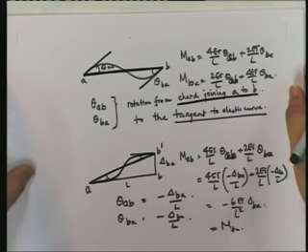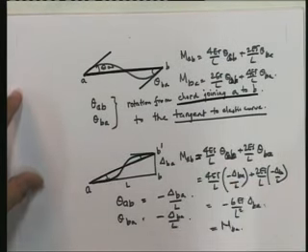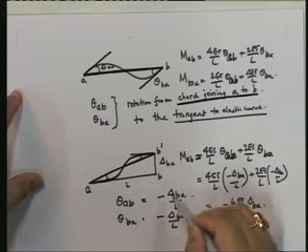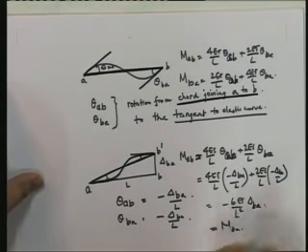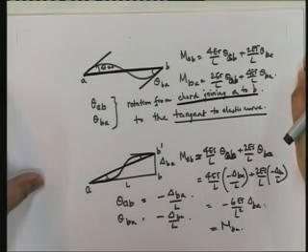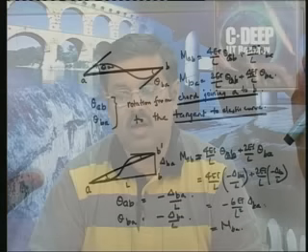So, therefore, there is no difference in the entire method. The only point here is that we have negated the effect of trying to take delta BA in the equation. We have simplified our slope deflection equation to just containing 3 terms, one containing theta AB, one containing theta BA, and one containing delta fixed end moment. Okay. So, essentially you may ask, what is the reason behind this? We will slowly come to what the reason behind this is, okay. But the point that I am trying to make is that this definition of theta AB and theta BA from the chord to the tangent of the elastic curve is completely equivalent to the previous definition. The only thing is that in the previous definition you had theta AB, theta BA, delta BA, all these as terms, and here you only have theta AB and theta BA.